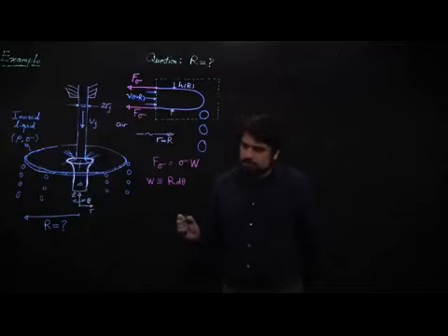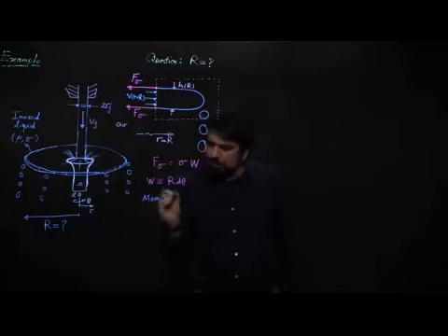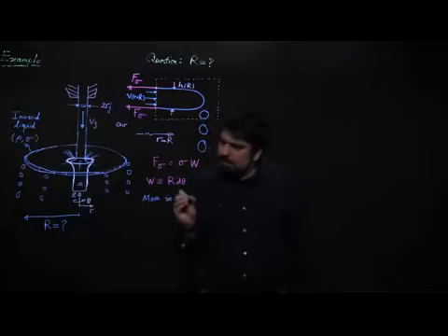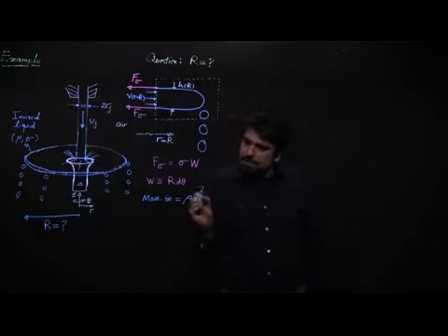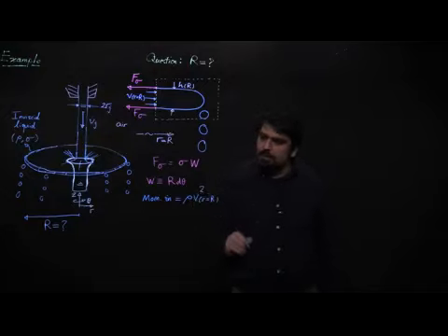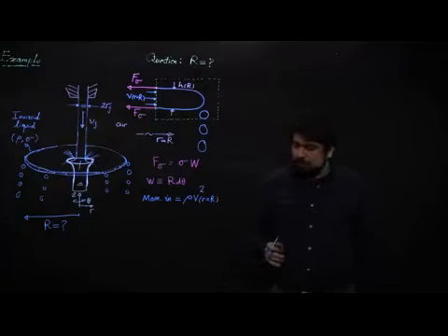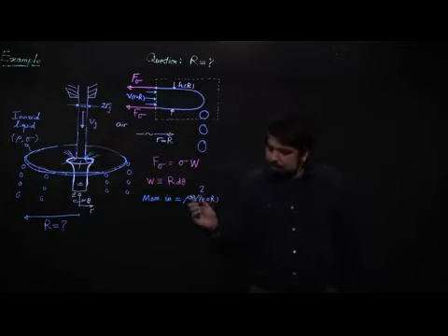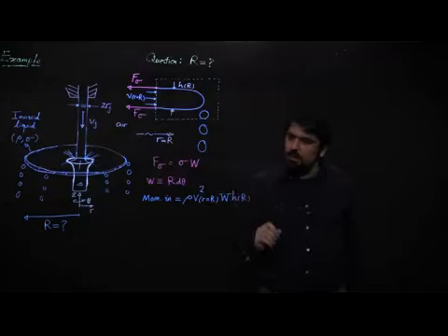the system? So the momentum that is coming into the system, which I show as momentum coming in, is nothing other than the density of the liquid, rho, multiplied by the velocity at this position, which is r equal to r, v squared times density, rho v squared. That's the momentum flux that I have. I should multiply it by an area, and the area again would be the unit length that we are going into the board, which is W, and the height of this, which is h at position r.